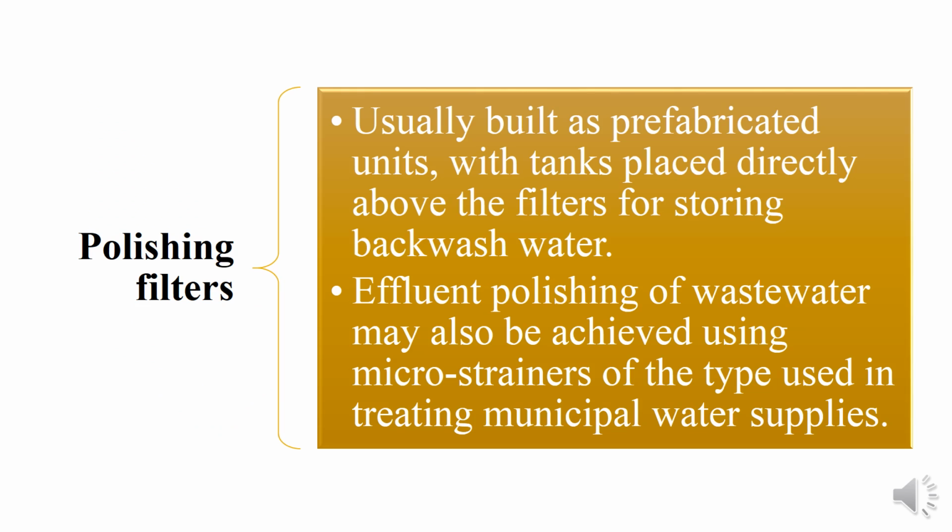Polishing filters are usually built as prefabricated units with tanks placed directly above the filters for storing backwash water. Effluent polishing of wastewater may also be achieved using micro strainers of the type used in treating municipal water supplies.